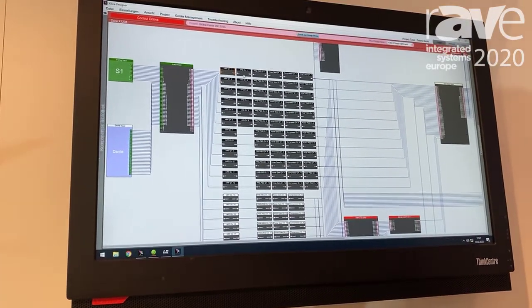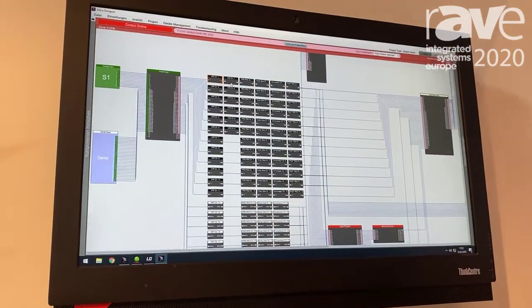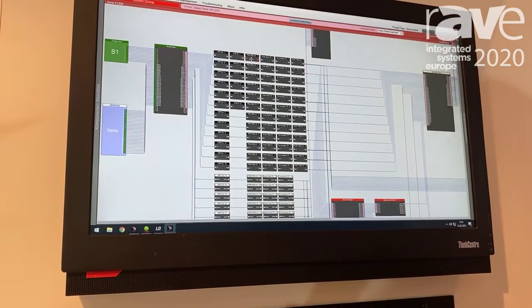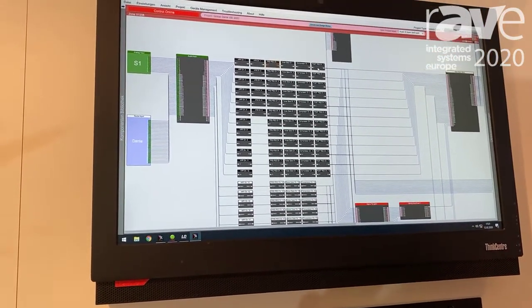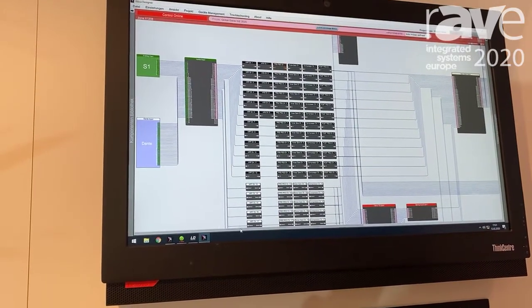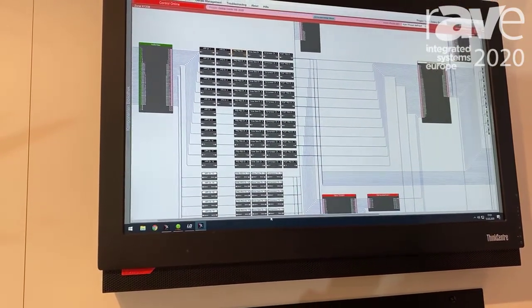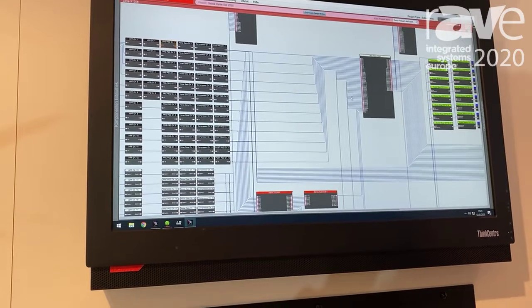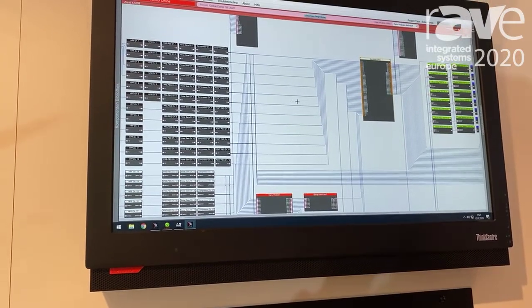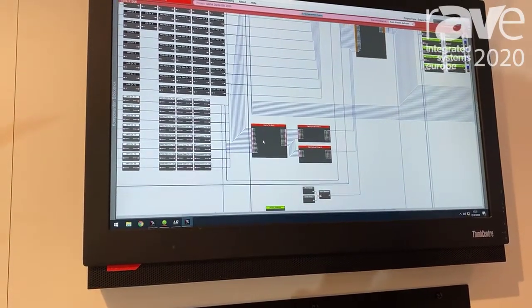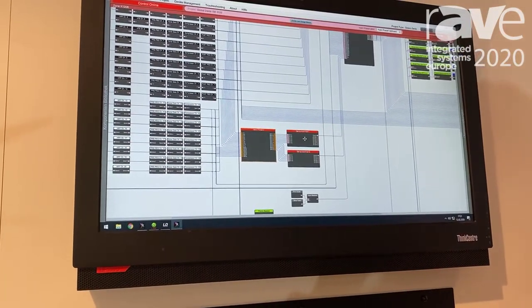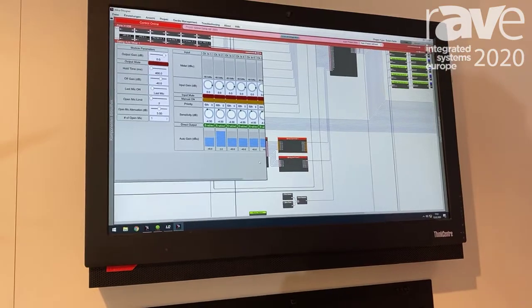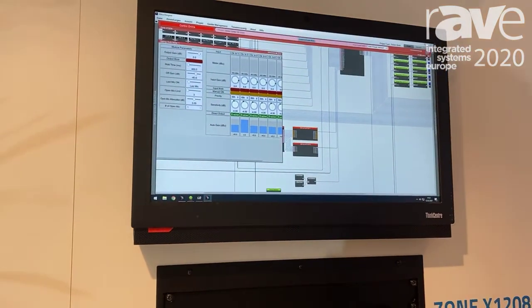There's a high pass filter, an automatic feedback suppressor, a 2-band pre-dynamics parametric EQ, noise gate, compressor, and a post-parametric EQ. So once you finish processing the input signals, you can send them directly to the main matrix right here, or before that you can send them to a smaller matrix here that decides which of the input signals go to the first 8-channel gating auto mixer, or the second one, which has 6 channels.